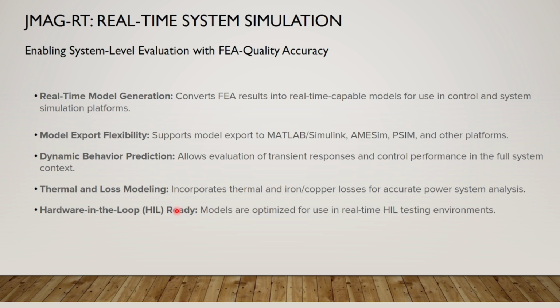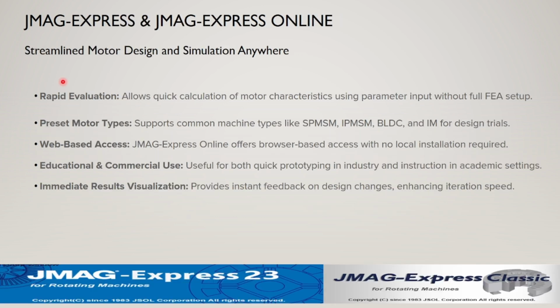Okay, so the next software in Jmag we are going to see is Jmag Express. Another type is Jmag Express Classic. So this is template-based design of your motors. If you are taking a PMSM motor or induction motor or BLDC motor or permanent magnet type of motors, it will have predefined templates. By using the template you can change the values of your motor's inner and outer diameters, magnetic types,